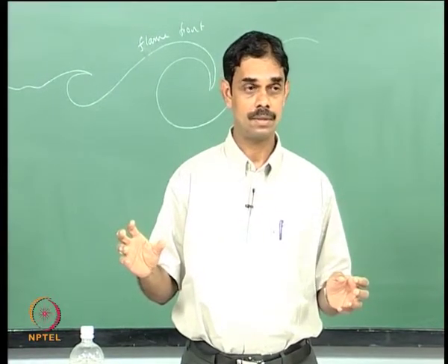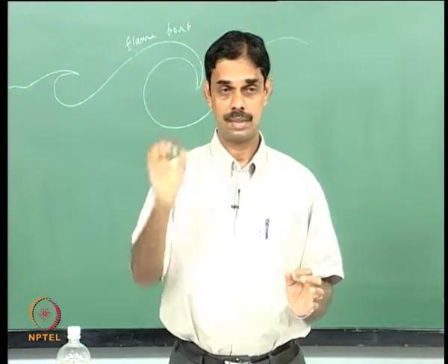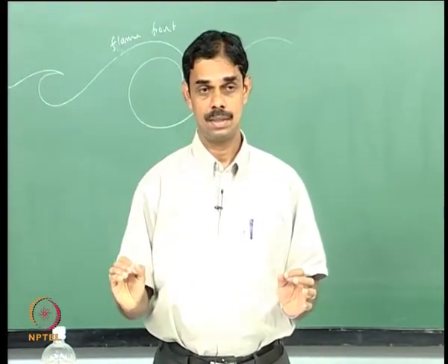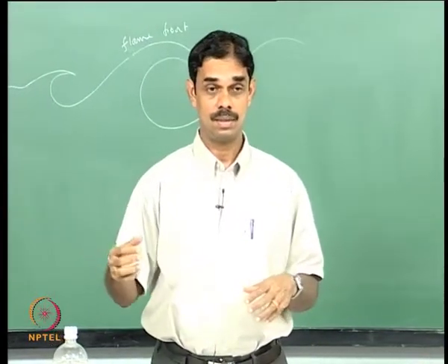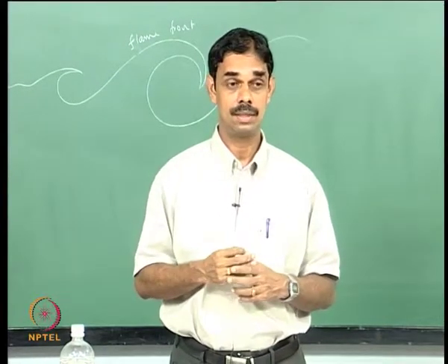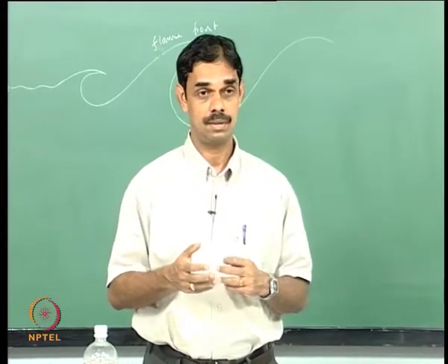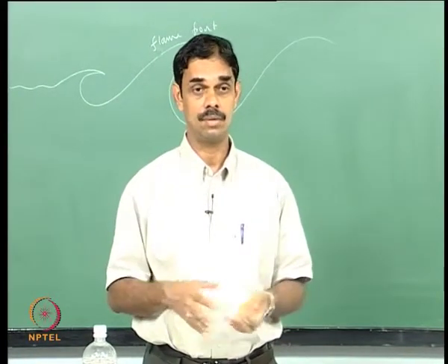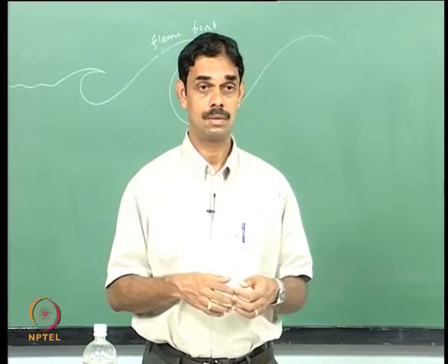You can have can burners, or you can have just an annular thing with swirlers. So you can have several swirl burners, not necessarily backward facing step, but often with swirl. They may have a step also, but there will be a swirler to have rapid mixing and so on, and that's possible. Can combustors are of course there, but the aircraft engines, they are annular. So the strategies could work.